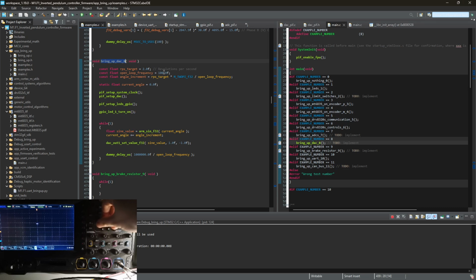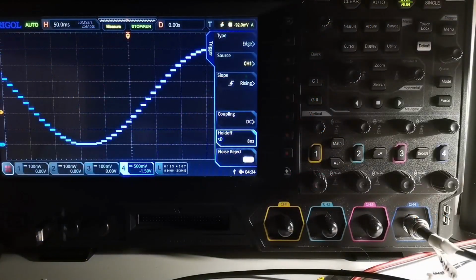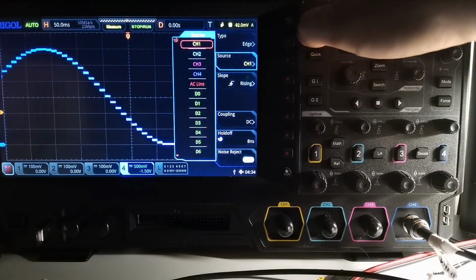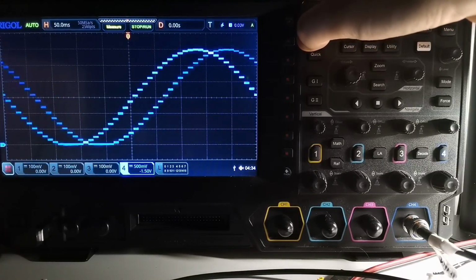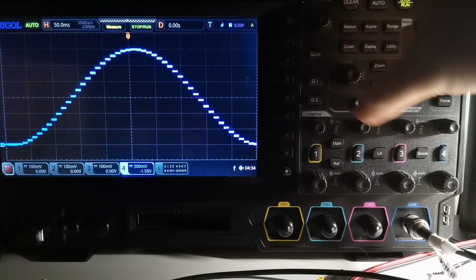Okay, hello. Okay, and it triggers 2 times per period, which I don't like. Sure, let's change it. Edge, type edge, rising. Okay, but it's supposed to be triggering only once. Right? Rising, rising, rising. Let's see. Oh, because it's supposed to be channel 4. Now that's much better. Or is it? It is not! Where is my trigger?